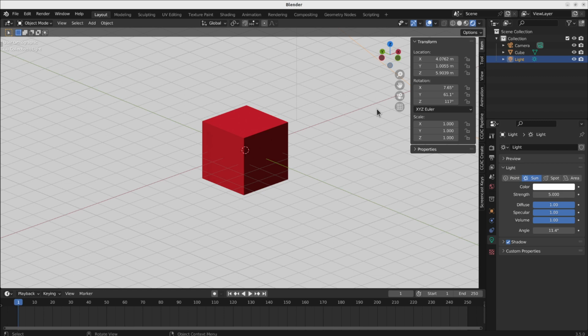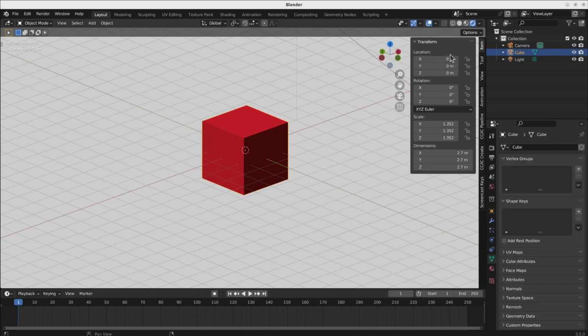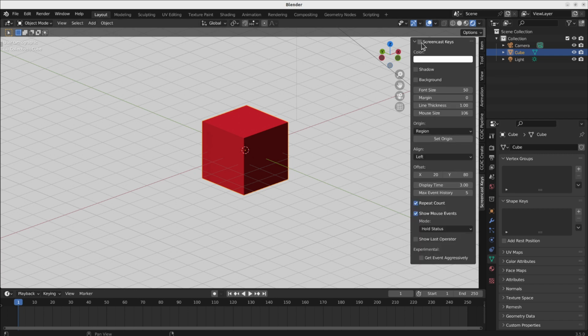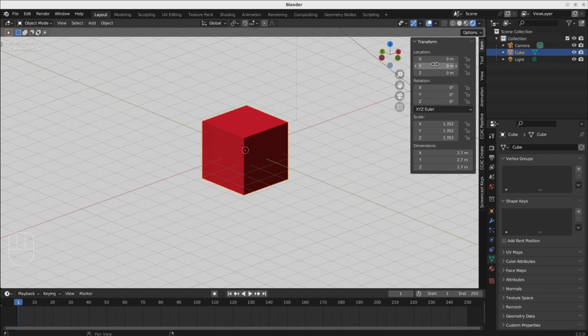Let's do something with scripted expressions. I don't know if you used this before, but you can animate objects in Blender by using keyframes. You go on it, and let me open my screencast. You go on there and press I to set a keyframe. But also, you can go in any field and start with a hash and then use the property frame to